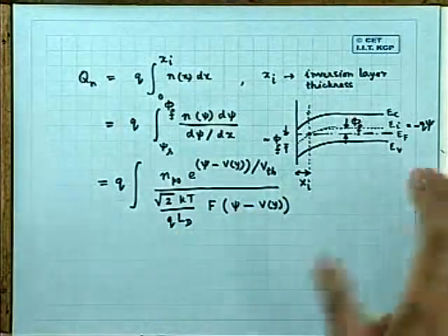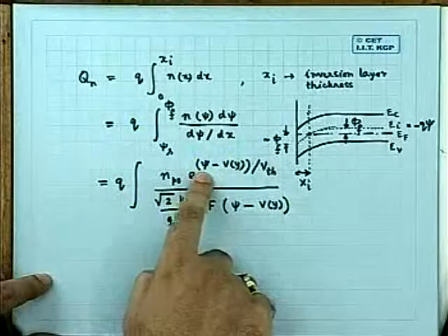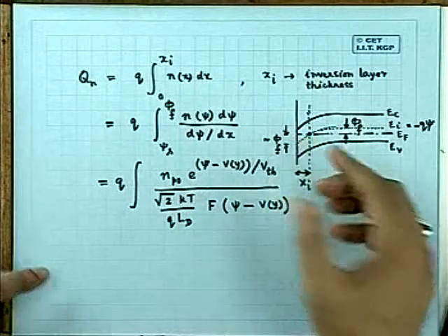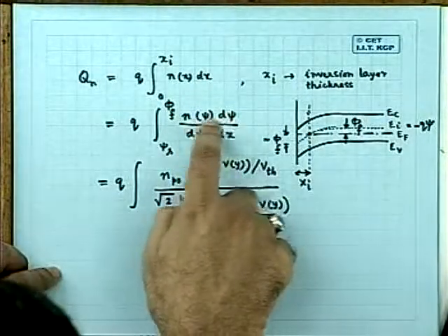Now actually in a device, the current is flowing, there is a Vy. There is a Vy, the induced potential due to the current flow. So that psi, whatever psi is, is a total psi. Now the total surface potential is the sum of that twice phi f and the drop. So what I am doing, I am subtracting that Vy from this in order to get this n psi expression.